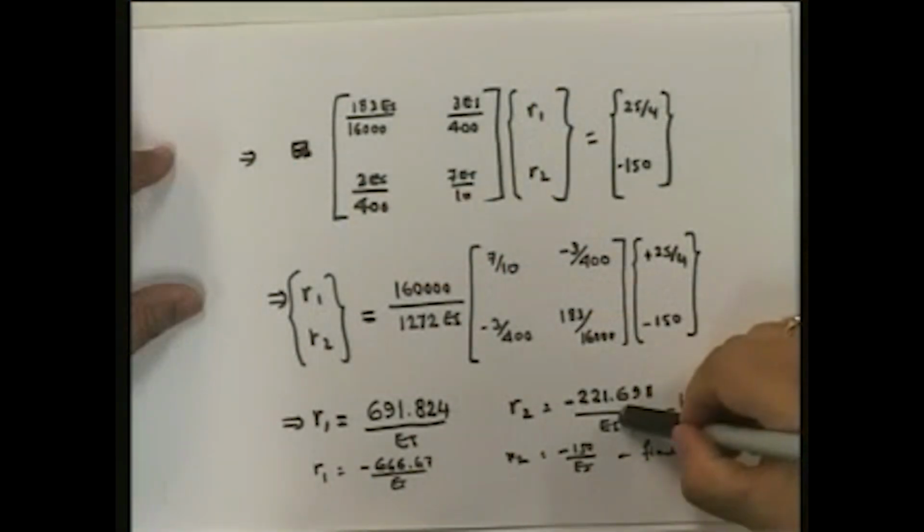The only difference is that in the previous case at C you had a fixed roller, and in the second case that we are dealing with right now, it is a hinge roller. So all we have removed is the restraint of rotation, and see what that has done to the displacement shape. It has had a significant effect. Look at the rotation. The rotation has gone up significantly.